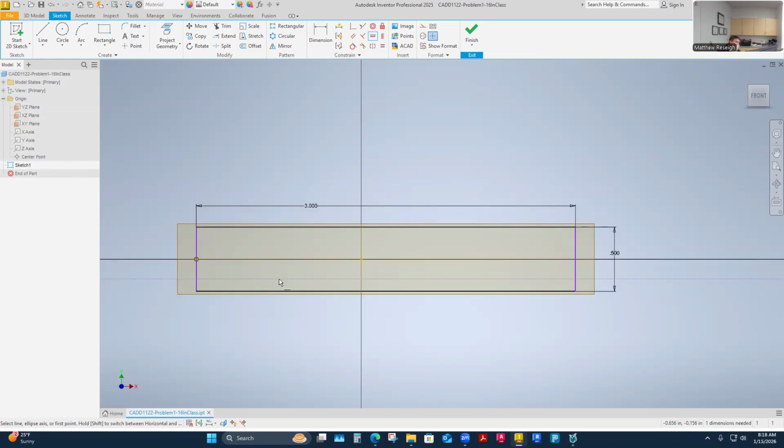So now two of my sides are constrained. And then I might do a vertical constraint on the midpoint of this line and to the center point. And now I'm constrained symmetrical over the origin point. Not that that would matter, but it's a quick way to constrain, with two horizontal and vertical constraints, not really any dimensions, just a dimensioned shape and then constrained.